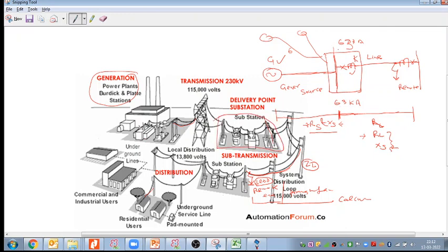So we will take that fault current at the substation location, right? So 63 is at my substation. If I go away, it will reduce, obviously it will reduce because some impedance is being added, but how much it reduces will depend on the conductors also. So I think this is making some sense.